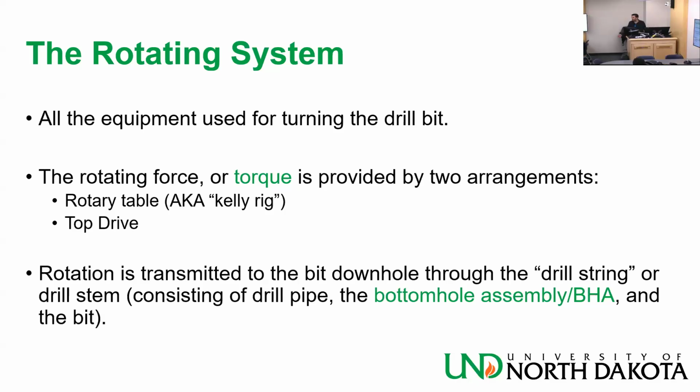And we said the drill string is composed of the drill pipe, the bottom hole assembly, and then the bit. Bottom hole assembly is one thing, which can be a lot of stuff, as you know. It can be a logging while drilling tool, it can be a rotary steerable system, it can be drill collars, which are added to basically drill pipe that is very heavy and thicker, and it's placed there to add weight.